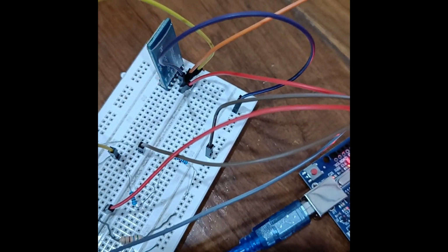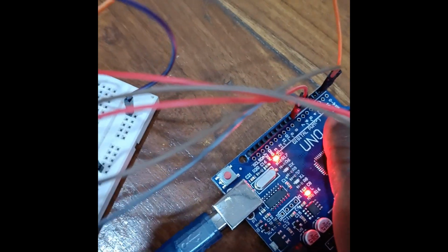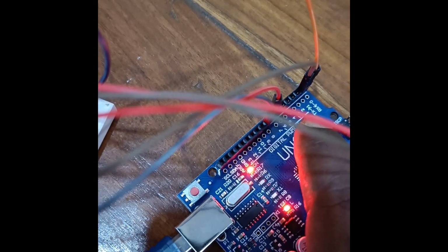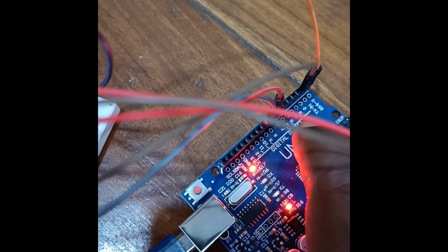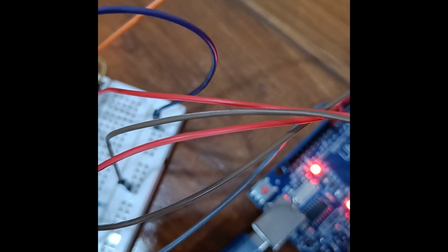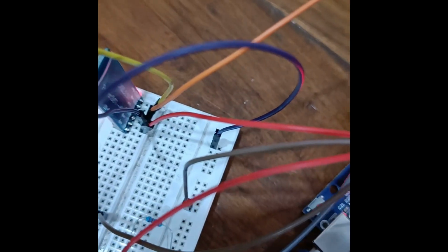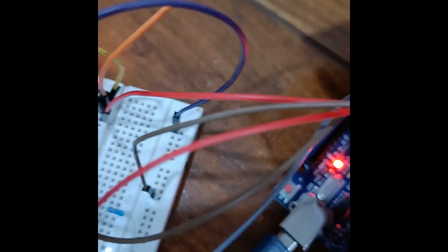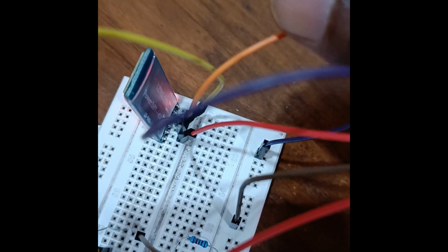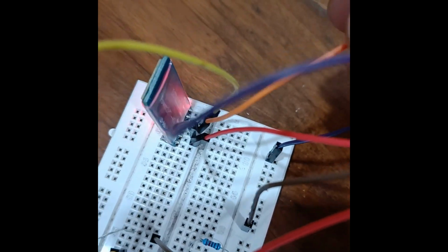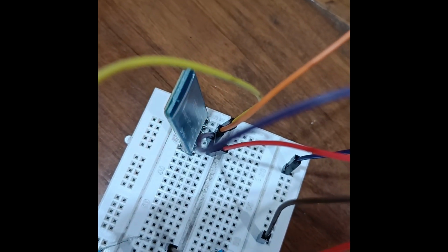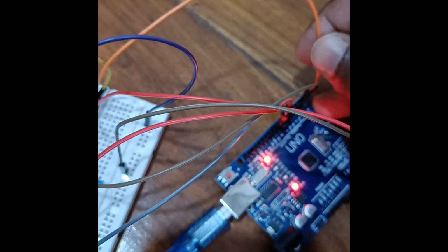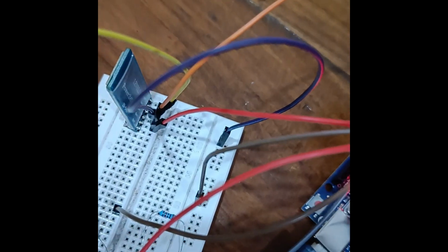The Bluetooth is my receiver. It receives, then it transmits to the Arduino board. So the receiver part is coming to the transmitter over here. And the next wire, the receiver of the Arduino, becomes the transmitter part, so it is going to the transmitting end of the Bluetooth module. I hope it is clear. The receiver of the Arduino is going to the transmitting end, because it is transmitting.